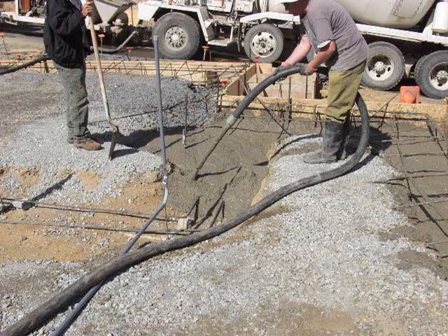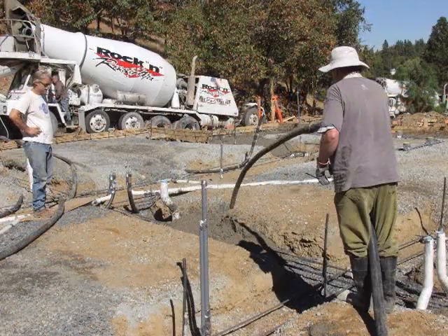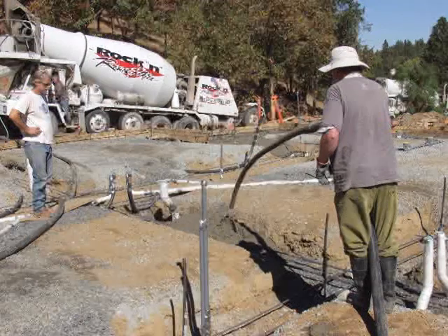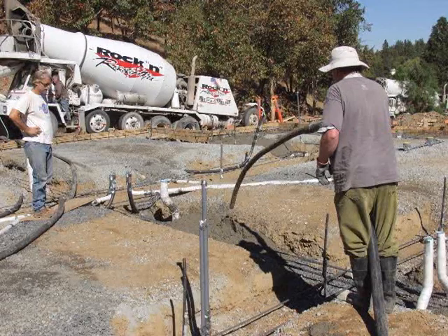Now you don't want to shoot it too far, because when it hits the ground, you might get separation between the aggregates and the fines and the water and all of that, and that will actually weaken the concrete. But you can see here is a great shot of the concrete being projected out. It hasn't quite hit the ground yet out by that second footing there. But this is just a great way to place concrete across a large slab where you don't have to be hauling wheelbarrows back and forth, which is otherwise what you'd be left doing.